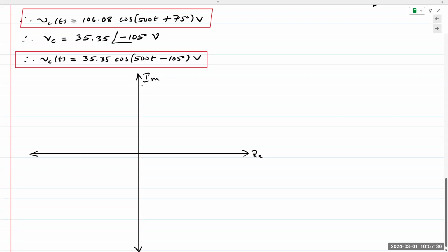Phasors and impedances we are representing as vectors, which are rotating counterclockwise in the complex plane. Real axis, imaginary axis. If you have a phasor or a vector with magnitude and phase angle, those are the only two things you need to plot. You first look at the phase angle. If it's a positive 15 degrees, then it's rotating counterclockwise. A negative phase angle with reference to the zero axis, the real axis, rotates clockwise.